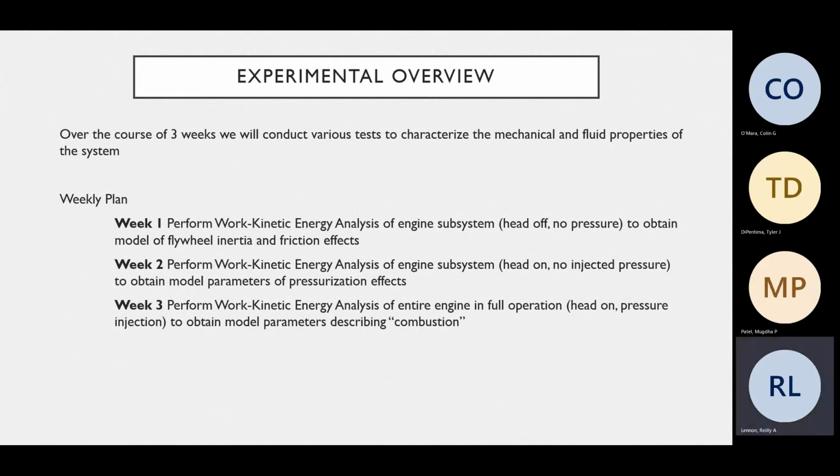Like I said, over the course of 3 weeks, we will conduct various tests to characterize mechanical and fluid properties of the system. Looking at the weekly plan, we're going to be performing a work kinetic energy analysis on all 3 weeks. On week 1, the analysis will be on an engine subsystem without the head and with no pressure. From that, we'll be able to obtain a model of the flywheel inertia and all the friction effects.